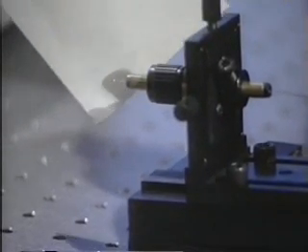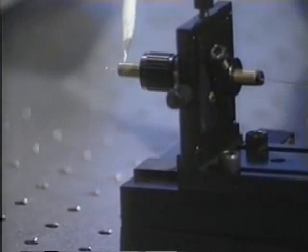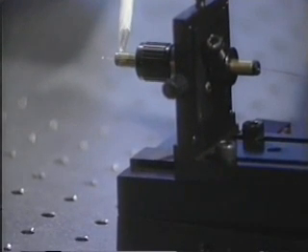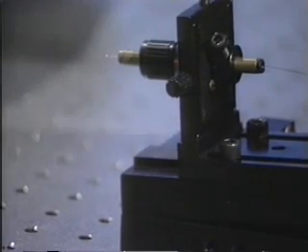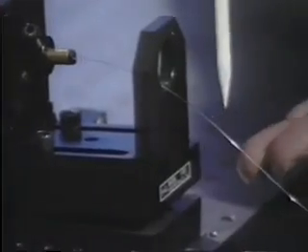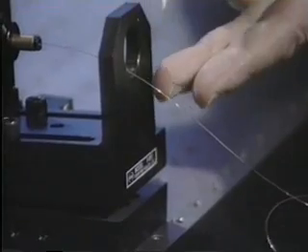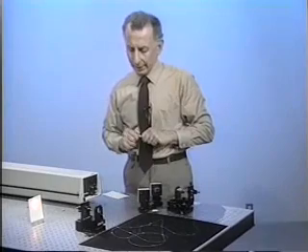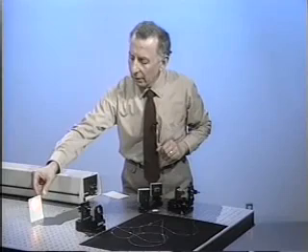Now, maybe we can take a close look at the fiber end here, which shows what you see over here. In fact, let me point to it. What you see over here is the cladding. Essentially, we've stripped the jacket, and what you see here is just the cladding, and this is the 125 microns. While over here is the fiber with the plastic jacket. So when you remove the plastic jacket, what you're seeing is just the 125 micron cladding. All right. So this is the fiber, and there's the output of the fiber.